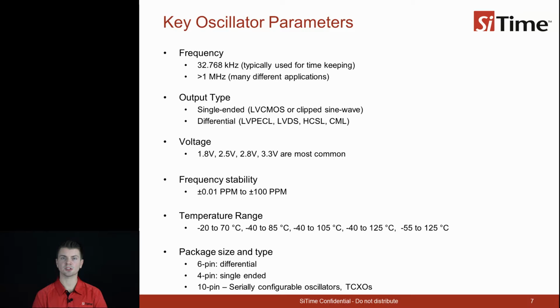Higher frequency applications often use differential signaling, which uses 2 signals which are out of phase by 180 degrees. Because the 2 clock signals are shifted in phase by 180 degrees relative to one another and also have lower voltage swing than rail-to-rail LV-CMOS, differential signals reduce the magnitude of electromagnetic emissions and crosstalk. Differential signals are sometimes used at lower frequencies for reduced EMI and better signal integrity. But above 200 megahertz, differential signaling is almost always used.